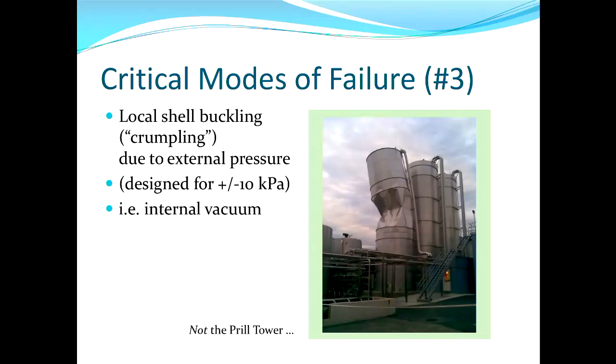That external pressure puts the vessel's shell in compression. You can picture that. Normally, if we've got an internally pressurised vessel, the vessel's shell is in tension. It's actually quite an efficient way of containing fluids under internal pressure. But under external pressure, there are all these problems associated with thin-walled pressure vessels.